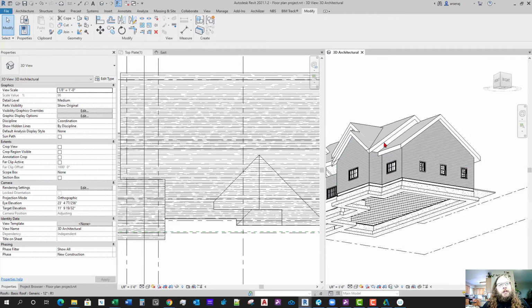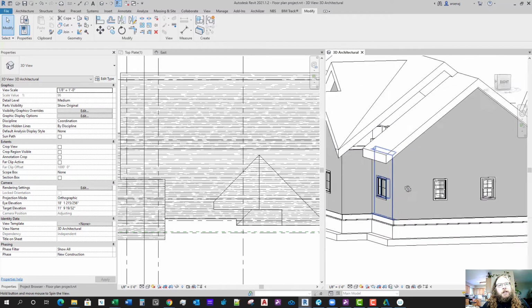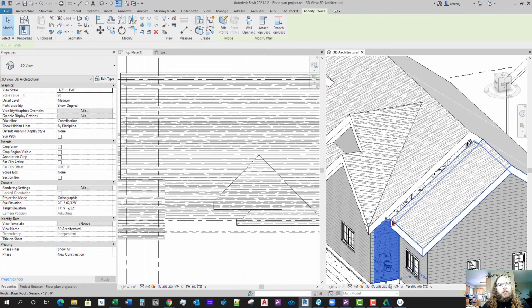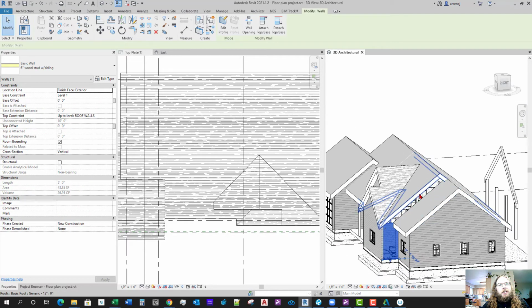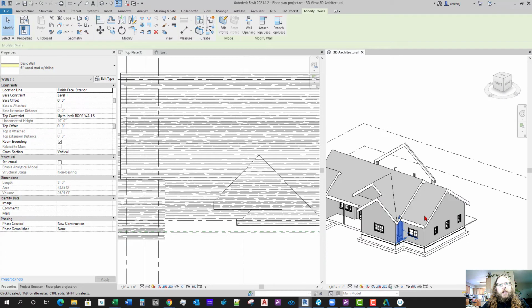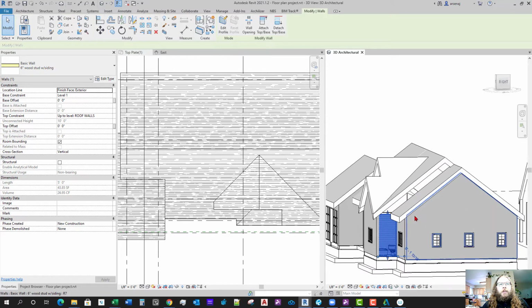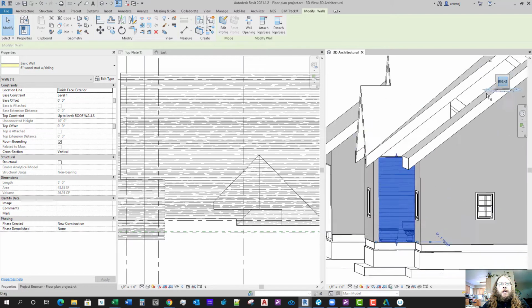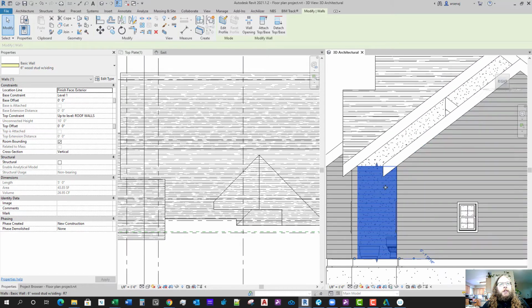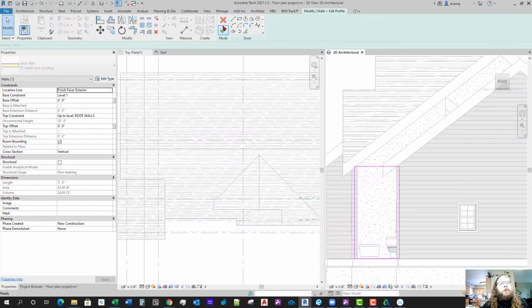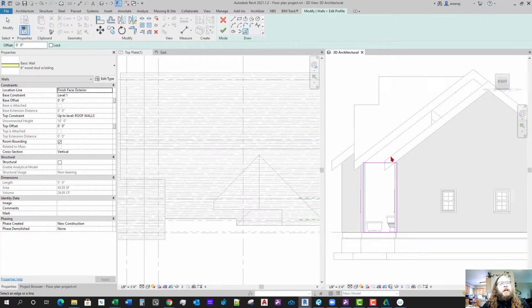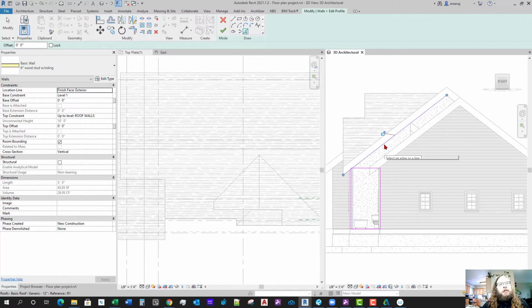We're almost there. This little opening here. We could attach to this roof, but it's only going to attach the wall here. But we have interior wall underneath here that won't be able to attach. So let's get the right front view, and we'll edit the profile like we did on that other wall. So edit profile, pick lines. We'll pick the bottom of the eave here,